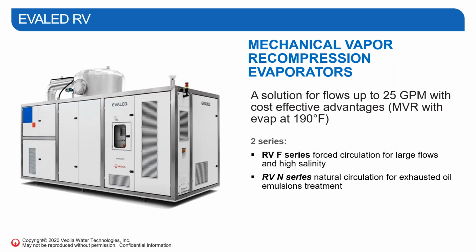The last one that we'll talk about is mechanical vapor recompression. So we'll go over a little bit more of a detailed explanation of this in a few slides. But the point here is that it's a bit less of a vacuum. So we're evaporating water at 190 degrees Fahrenheit. But it does handle much larger flows. So we're up to 25 GPM with this.